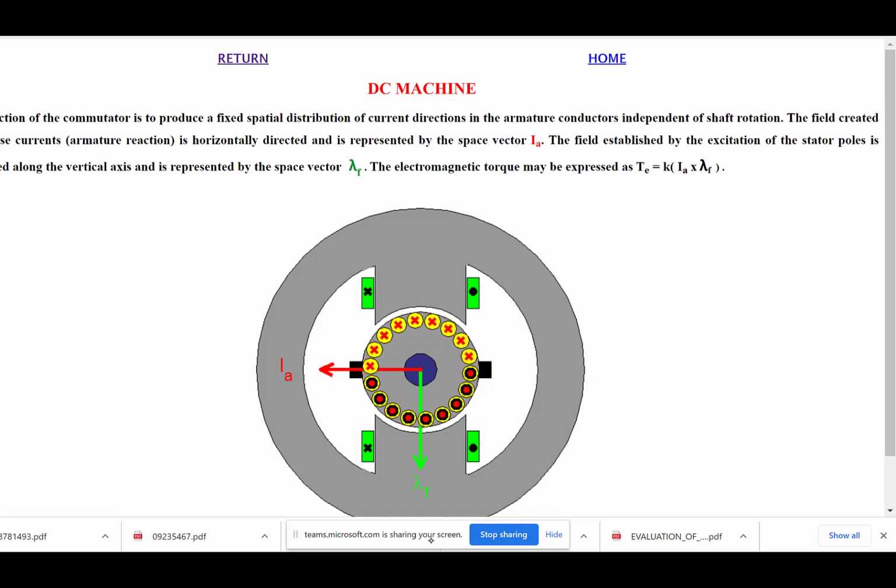And the Q is the torque, the D is the flux path, if you look at it from a machine standpoint. And if anybody's heard of DQ representations of machines, you can actually represent any rotating machine in terms of these two axes, D and Q. And there's a lot of very cool control things you can do. If you can add power electronics and microprocessors and field programmable gate arrays, you can produce some very cool stuff.